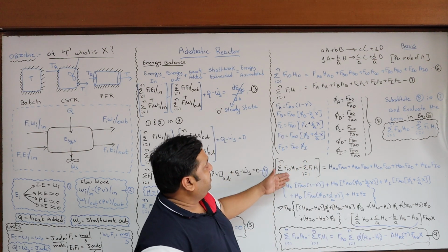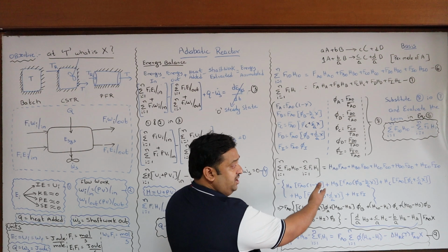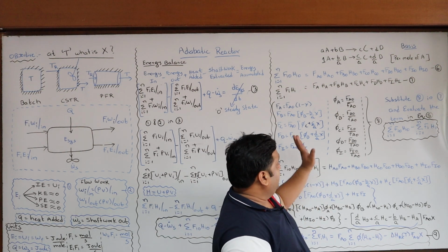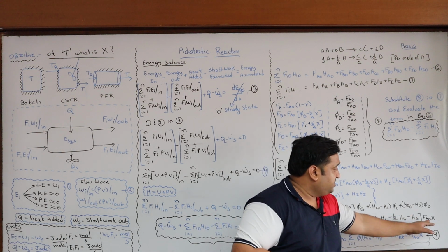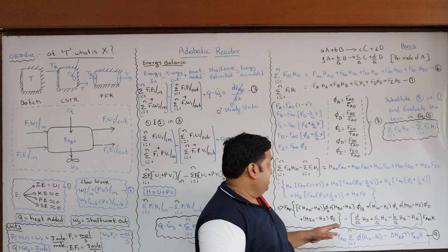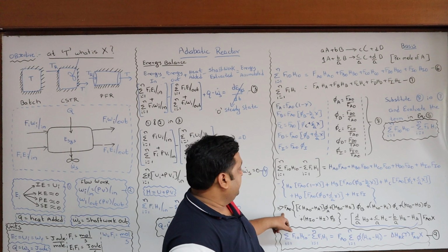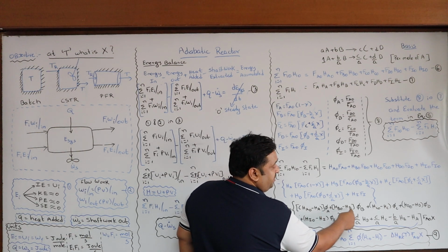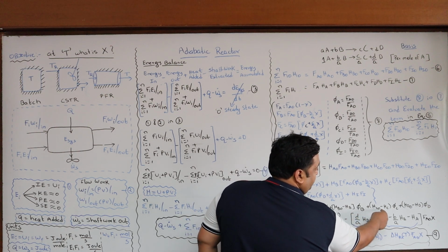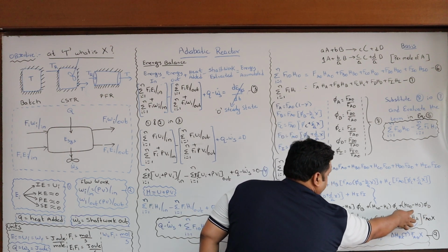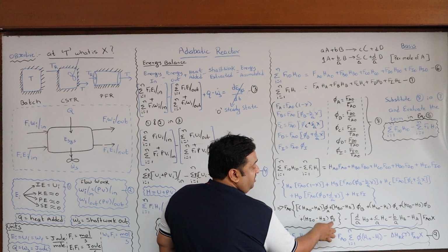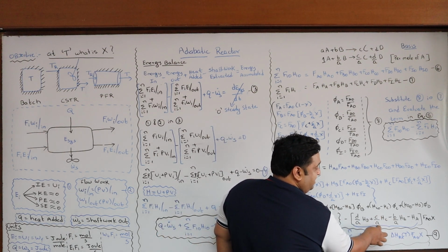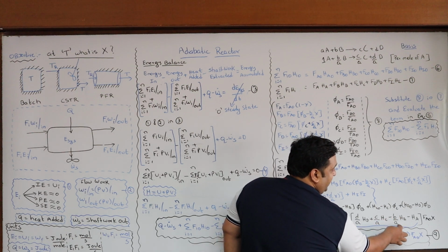Okay. If you do that, if you common out a few things and separate out the conversion term and the other terms, you get Fa0 into Ha0 minus Ha into phi a, plus Hb0 minus Hb into phi b, plus Hc0 minus Hc into phi c, this is in terms of phi d, plus Hi0 minus Hi into phi i inerts, minus d by a into Hd plus c by a into Hc minus b by a into Hb minus Ha.